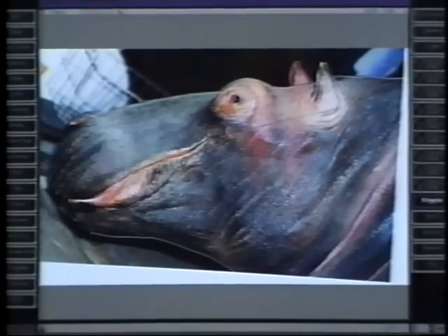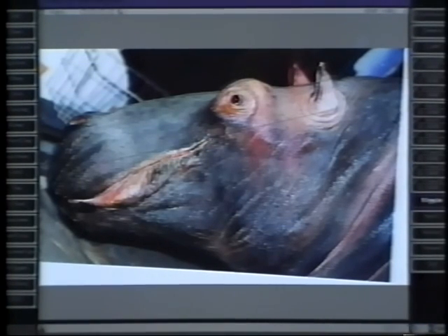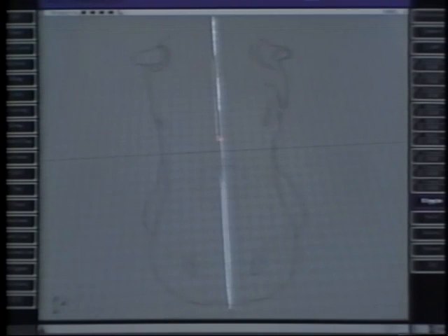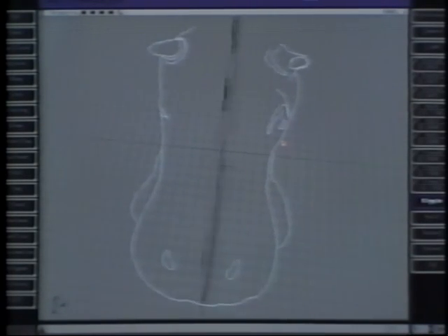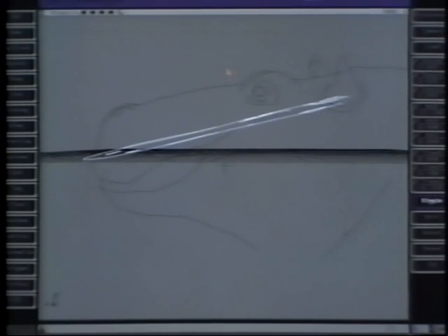For many models, your design process will begin outside of the computer with drawings, clay models, or researched photographs of a real subject. You can put these images into a rotoscope wire window and draw curves to outline them. Once you've got key contours from 2 or 3 angles, you can position them in space as a 3D reference.